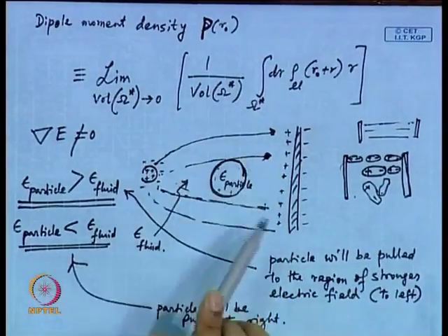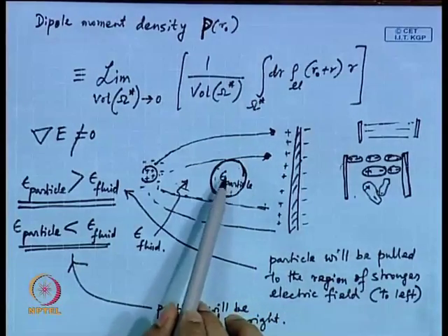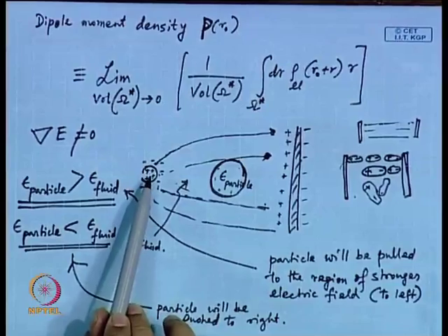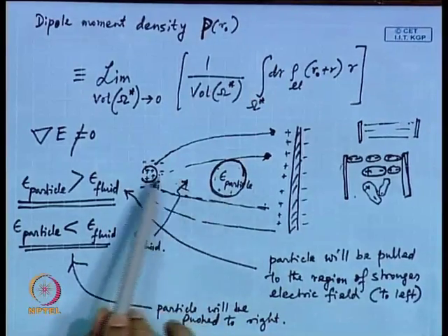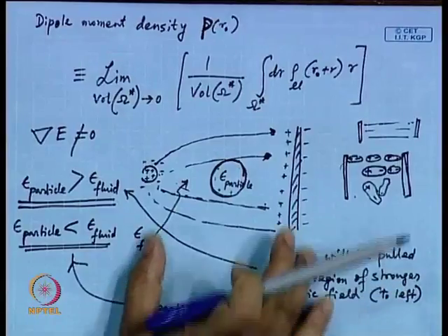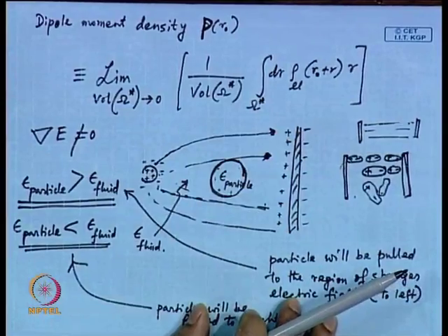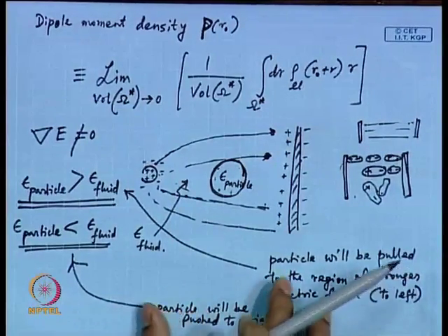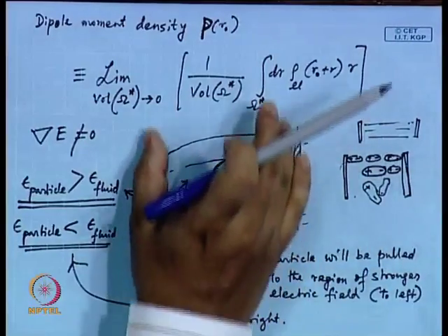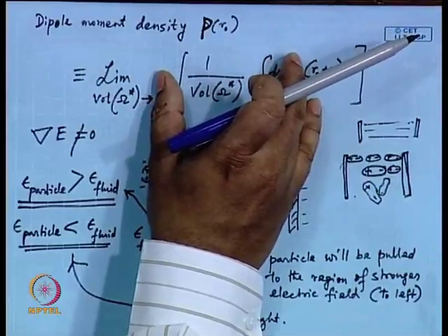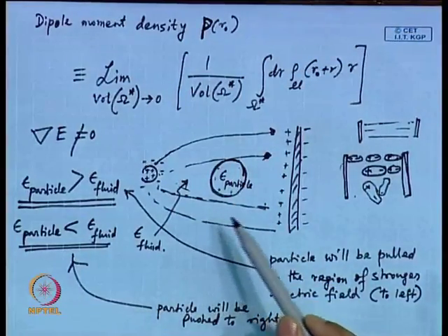So, depending on the f sub particle, you expect some particles will be pulled towards the point electrode and some particles will be pushed away from the point electrode. Okay. One thing you could do is use this channel in a field flow fractionation mode. You are already familiar with what field flow fractionation means. That means you are collecting the sample, but by the time it comes out, since you have a parabolic velocity profile.